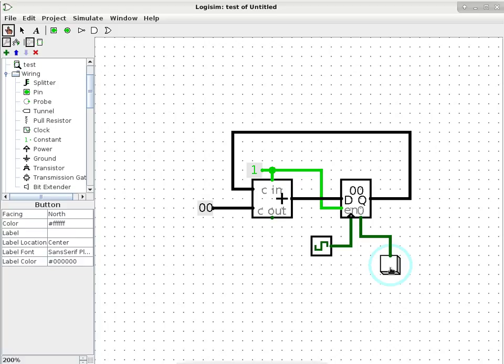So are there any questions about this kind of little circuitry? Now, this circuitry, just for counting or for timing, would not have been possible without a clocked or an edge-sensitive D flip-flop. Because if you do not have a register in between and you just hook up the output of an adder back to the input of the adder, the adder is just going to go crazy because it will update the output based on changes to the input. And it will just do it on a continuous basis, which makes no sense, okay? Because you have no control over when it should increment, and you have no control over the actual value either.